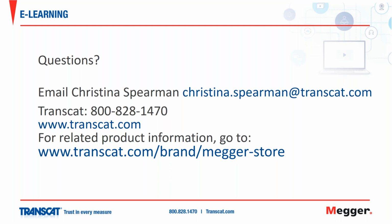You want to have readings, as we mentioned, say during installation or commissioning of equipment, you want to set a baseline so that as you do future tests, you can look for that increase. So I think the question there is, what are acceptable levels of resistance? And that's going to vary greatly depending on the application and the equipment that's being tested. But just in general, we would refer you to the manufacturer.